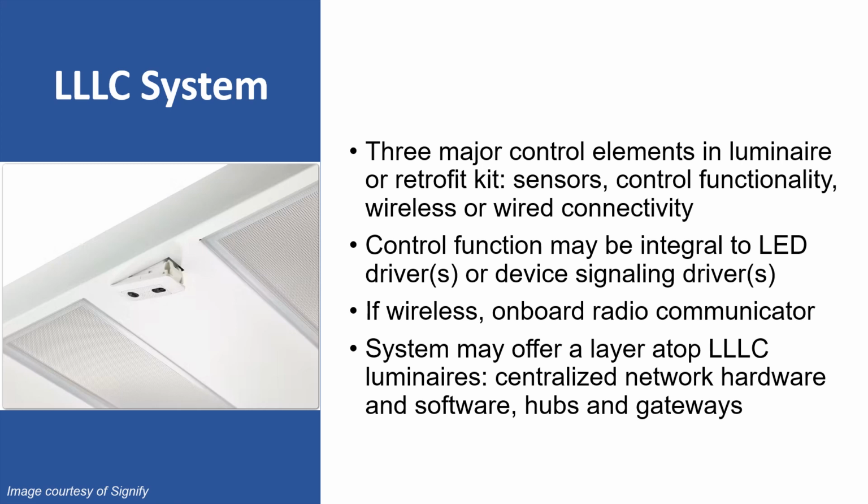Wireless connectivity is achieved via an onboard radio transmitter and receiver connecting the luminaire to a network with various standard and proprietary protocols available for this job. If these elements are from a single manufacturer and installed in the luminaire at the factory, compatibility is assured, controls installation is simplified, and the luminaire arrives programmable or with a pre-programmed sequence of operation.